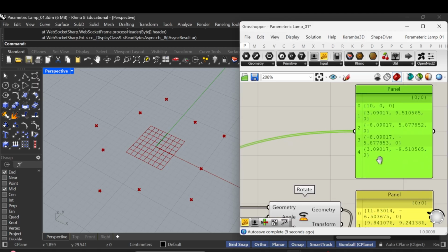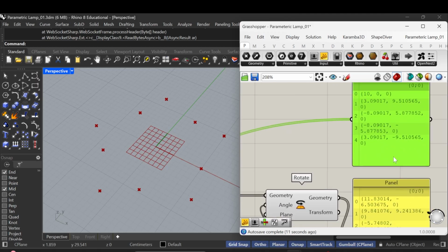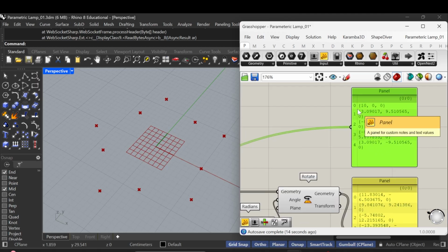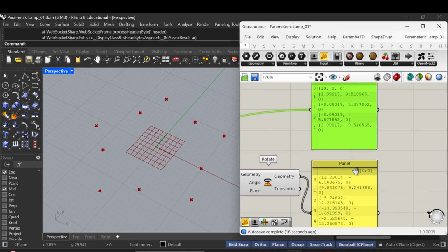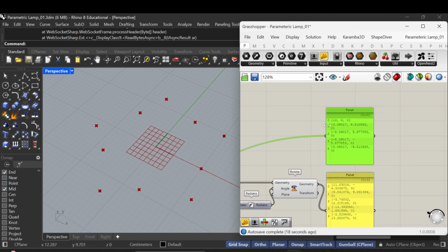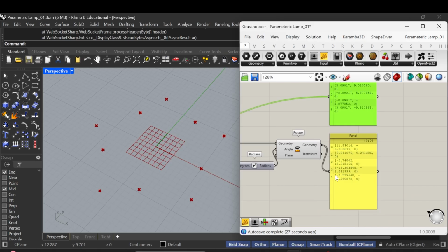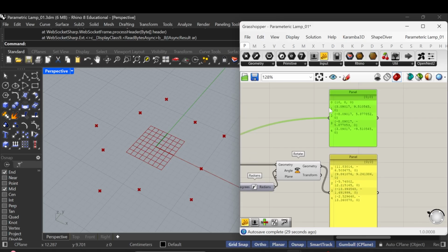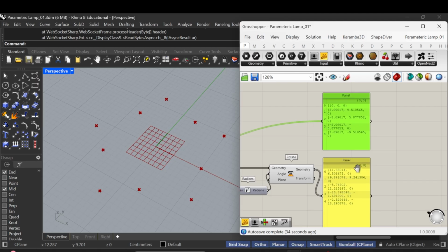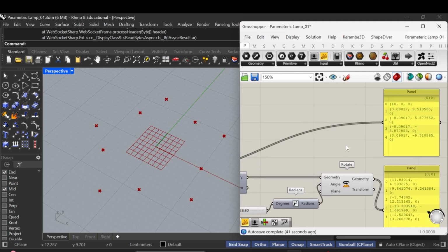So now I need to weave these 2 lists. Otherwise, if I use a polyline, then the first list is going to be connected with a polyline, all those points, and then it's going to go after the second list. No, I don't want to do that. I want to connect 0 from this list to 0 from the second list. The 0 from the first, 0 from the second, 1 from the first, 1 from the second. That's the kind of order that I want.